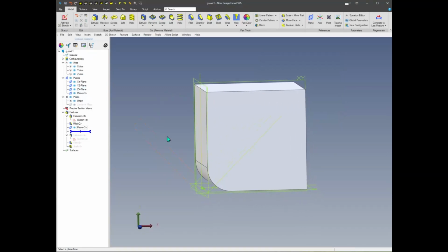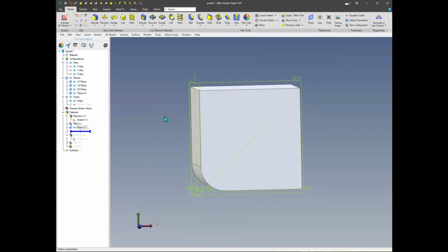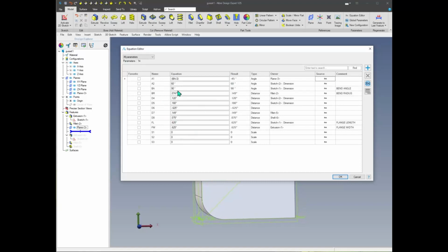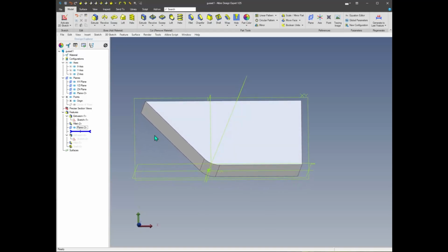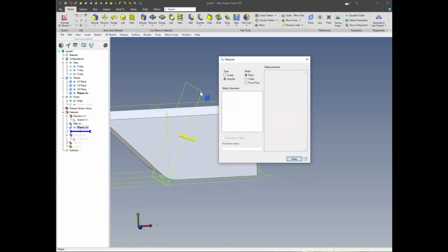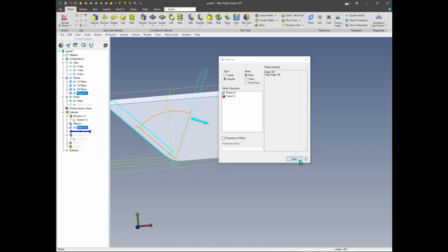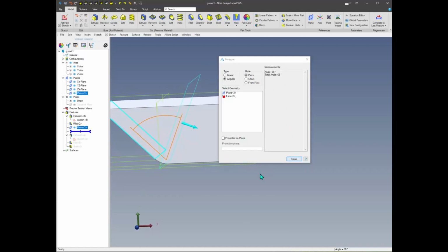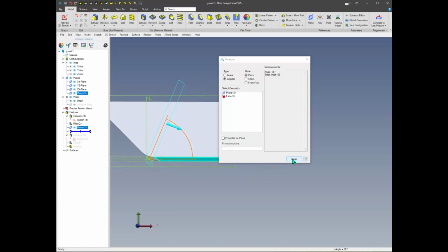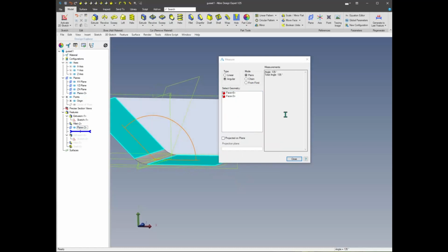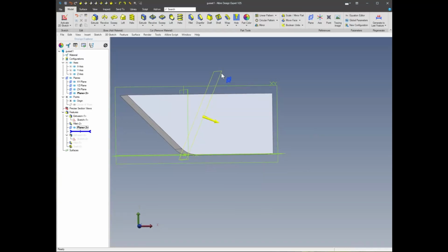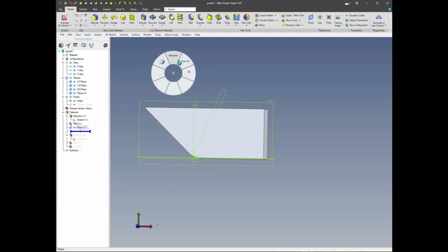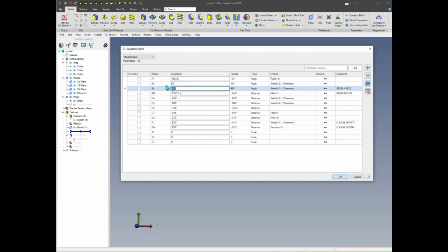then we're okay. Now to test this to make sure that that's going to follow whatever our bend angle is, let's come in here and bring up our bend angle. And let's say our bend angle is 45. Now it changed our angle from this face to this face at 45. And what we should have between this plane and this face, we have 68, and between that one is 68 because our included angle here is 135. So we're maintaining that mid-plane position for this sketch plane between these two faces. So let's go back into our equation editor, change our bend angle again back to 90.